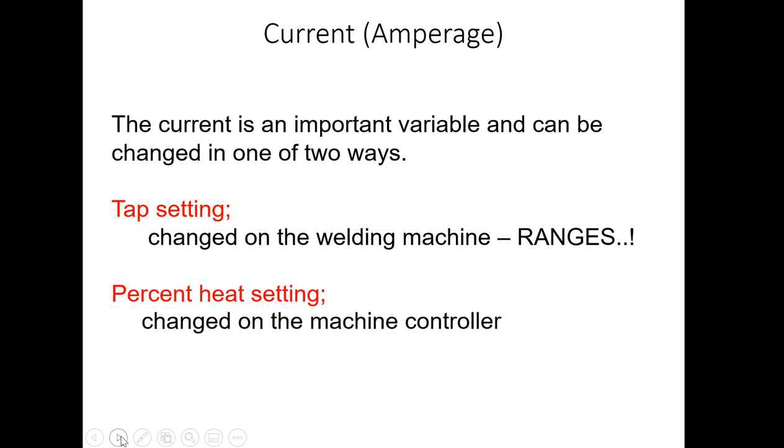So they give us tap settings, and it gives us an opportunity to say what gear we're in. If you're thinking about a 10-speed bike, are we in second gear or third gear? Should be in fourth gear. You need to actually do some math and figure out, based on your thickness and your current and what you've assessed before you even start.